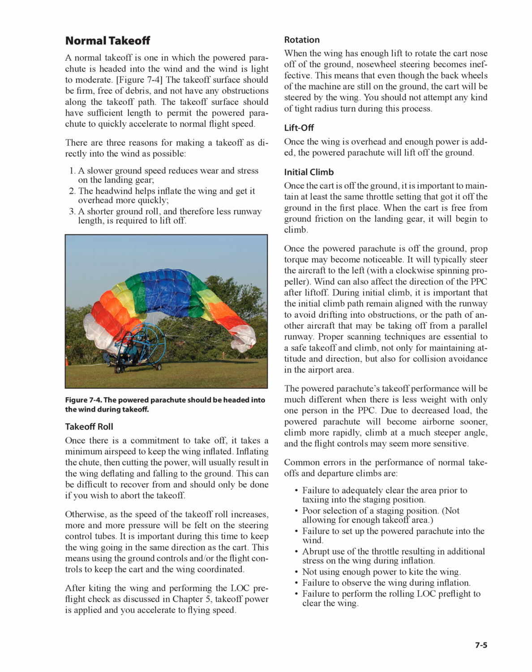Rotation: when the wing has enough lift to rotate the cart nose off of the ground, nose wheel steering becomes ineffective. This means that even though the back wheels of the machine are still on the ground, the cart will be steered by the wing. You should not attempt any kind of tight radius turn during this process.